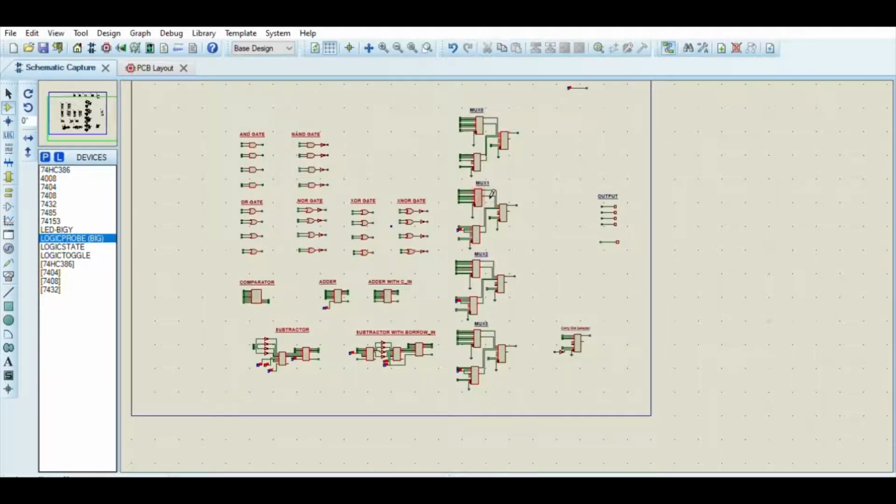The most important circuit of the whole simulation is the 16 to 1 multiplexer circuits. We have to use 4 of them, as you can see here. 4 of them are used as there are 4-bit input and output, and we have to implement a 16 to 1 mux circuit as we need to select among 13 operations through the selector pins.